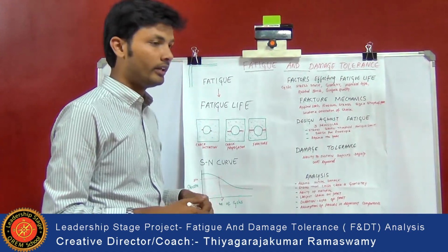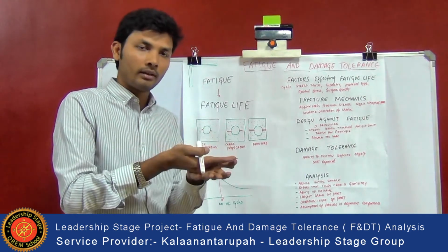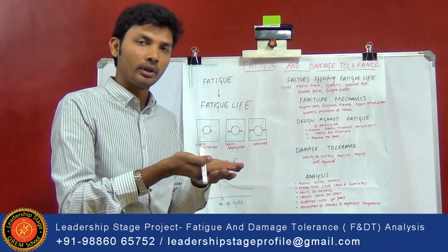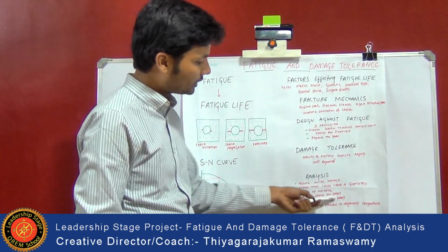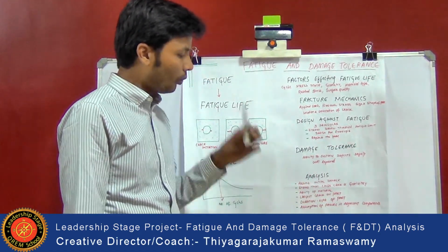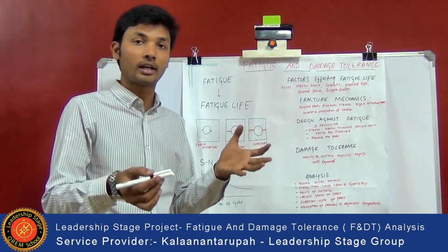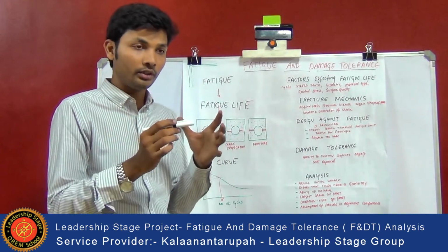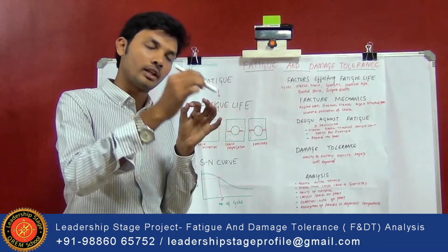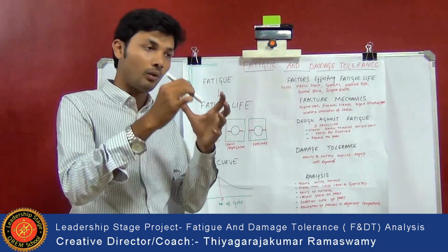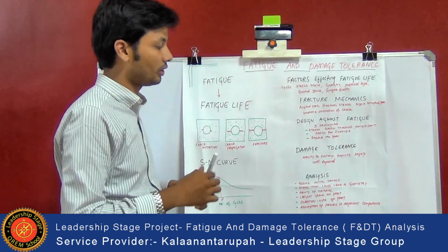Then the ability of the material. We need to see if the material can withstand the load being applied, and whether that is within the limits of the endurance point. We need to check all these things about the material as well. Also, to study damage tolerance, you need to study the largest crack on the part. A few components will have 3 or 4 cracks because of weakness. You will have the fracture first at the point with the large crack, so we need to study what exactly is going on at that largest crack.